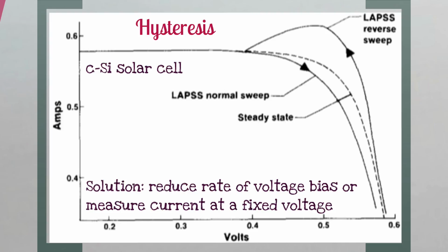And this is not good because in an actual solar panel, you might be changing the bias slightly. This is, by the way, what a smart inverter does. It changes the bias slightly to get the maximum juice out of the solar. So if you're doing that and you don't know exactly what the response is, because these are two possible things that can happen in terms of resistors, that's a big problem. That means your power electronics, your control circuitry for your power electronics, will not work properly.